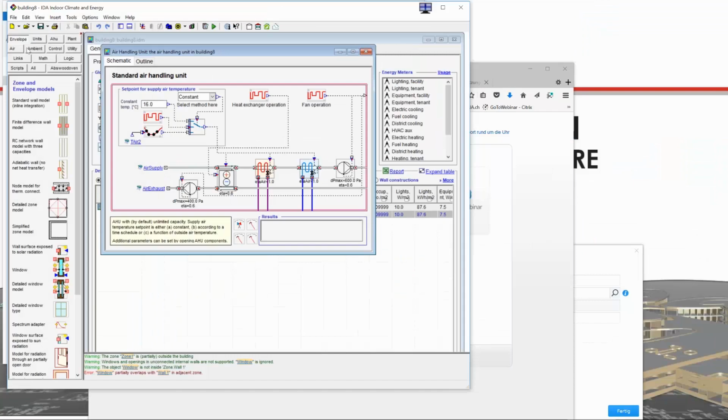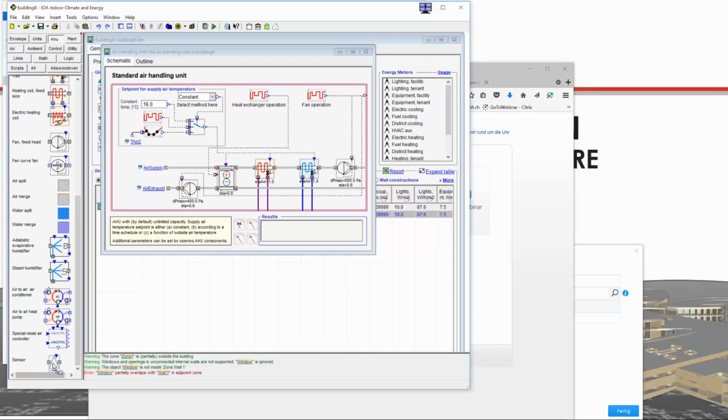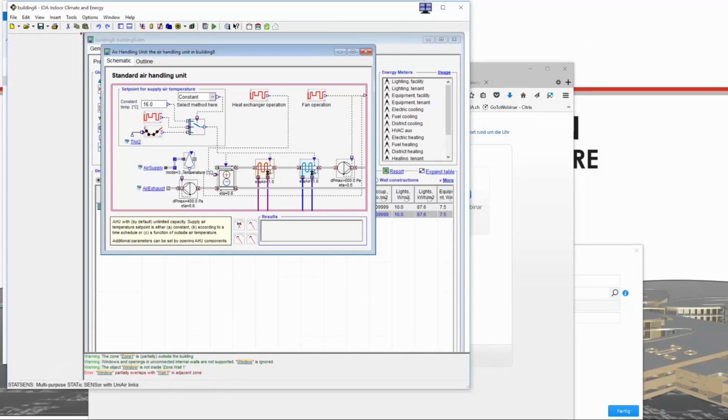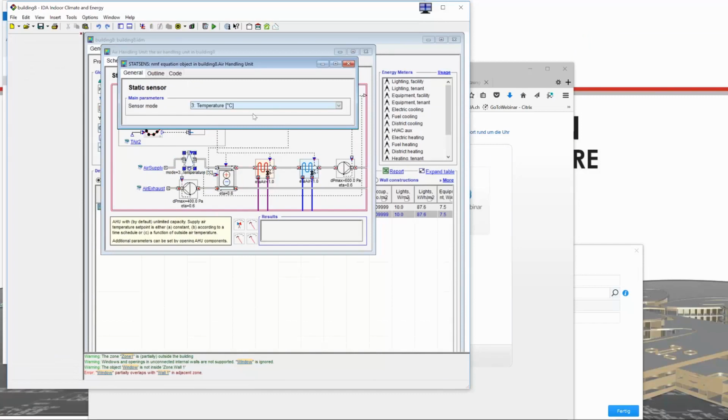Okay. I just need to check something, because in the air handling unit you have this sensor. For instance, you can always insert such a sensor in any air channel of your air handling unit, and if you have it here at the ambient air inlet, you can sense ambient air, and here you can select between different sensors, and one of them is humidity ratio.